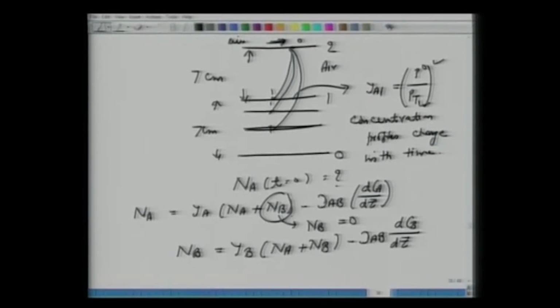Of course, if we make Nb equal to 0, it's easier to integrate these equations and obtain what we got earlier. But more important is, let's note down physically what it means that Nb equals 0. Air is stagnant, so this term is 0, but we have convective transport here, bulk transport, which is Yb Na, minus the second term, Dab dCb by dz.